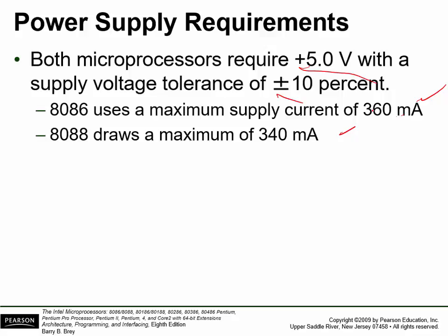So as we look at these processors, the power supply voltage is a key. The 8086 is a 5 volt processor. The 8051 that we're using is a 3.3 volt processor. The original 8051 was a 5 volt processor. It doesn't really matter so much, other than you have to be aware of what processor it is, and there are some interfacing problems you have to deal with if you're mixing them.